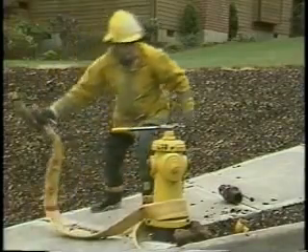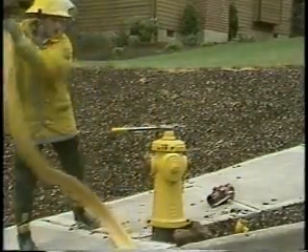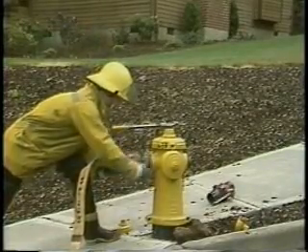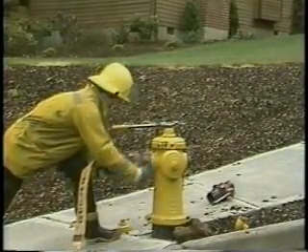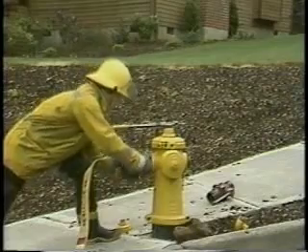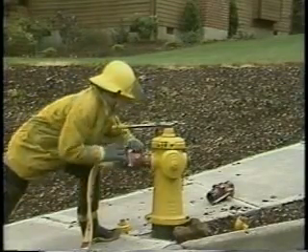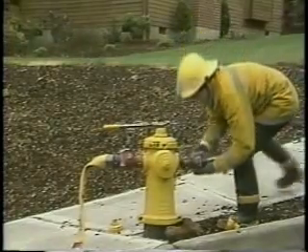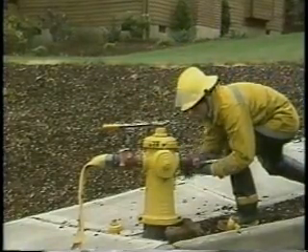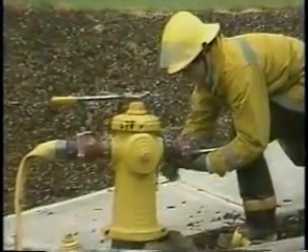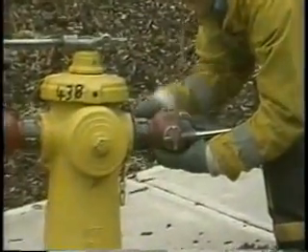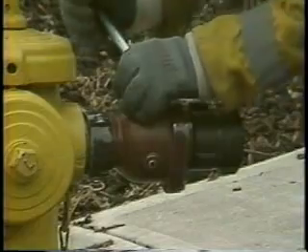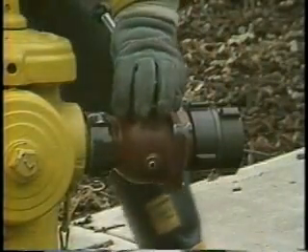Your policies will dictate what will be coupled to the hydrant, the supply hose, or one of many types of water flow control appliances. In this case, a hydrant gate will be installed on each of the uncapped ports. The supply hose will be coupled to one hydrant gate. The other hydrant gate will be installed in the closed position, ready to accept a second supply line if the need arises. Once all connections are completed and checked, the hydrant operator waits for the lay-in to be completed.